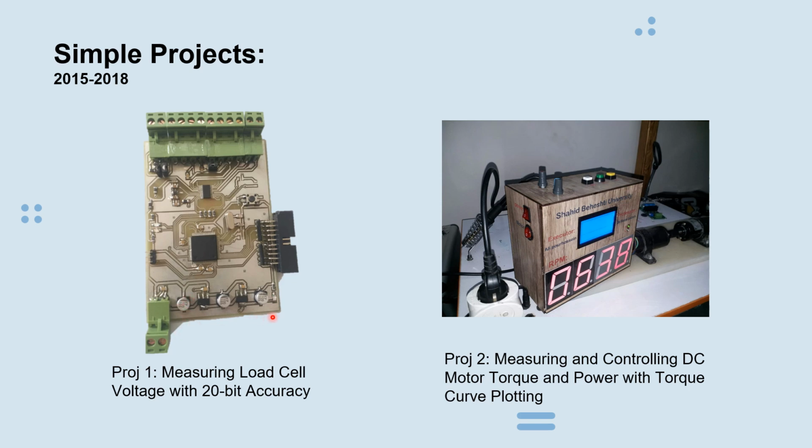For producing the PCB, first I designed it in software like Altium Designer. I designed this board in that software, and then sent it to a company that produces this kind of PCB, and they print these connections on a board. Then I can solder electronic components like ICs, microcontrollers, resistors, capacitors, push buttons, regulators, and other components onto this board.